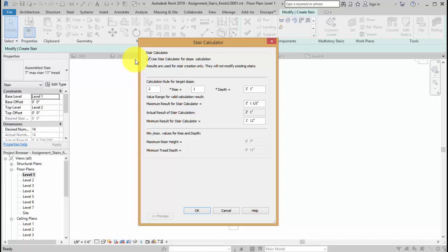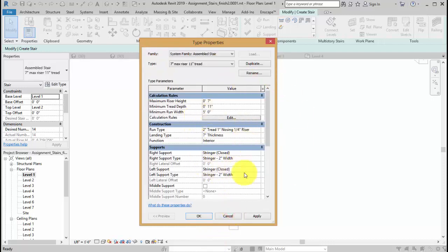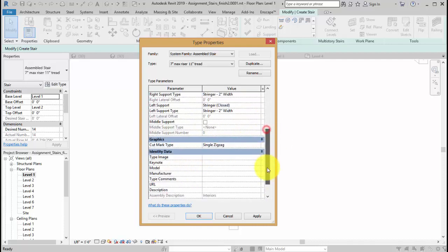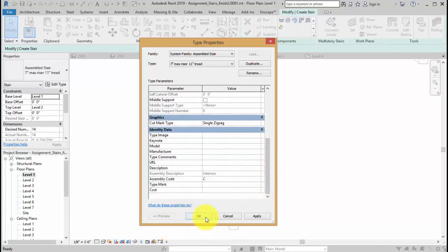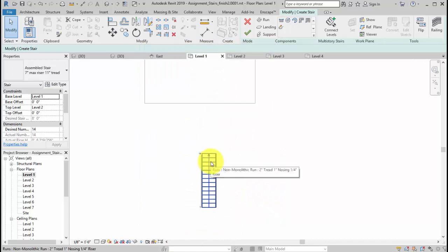You have your level set up. Just use the default one. So we're going to cancel that. And there are other things like stringers. There are all kinds of things that are related. And also the mark will be automatically generated when you go up leading to the second level, and it will have a symbol that breaks half of the stair when you're leading up. So nothing really worth it at this time. If you want to know more about it, just go read my extra pages about the stair generation guideline, the detail. Okay. Now we change the width, so it becomes 5 feet wide.